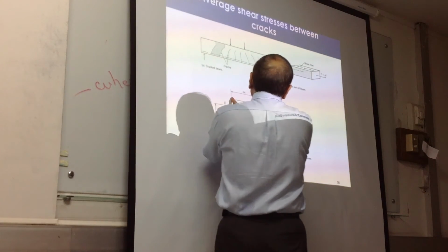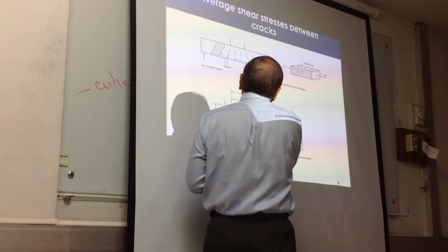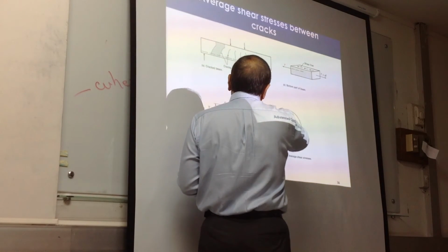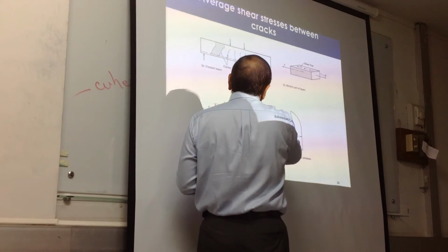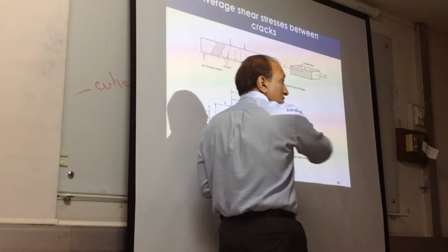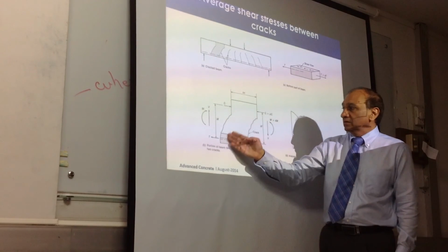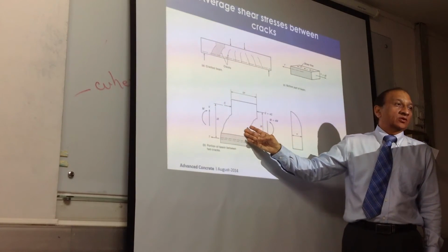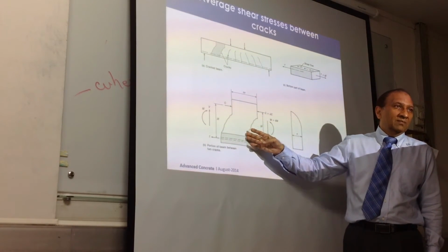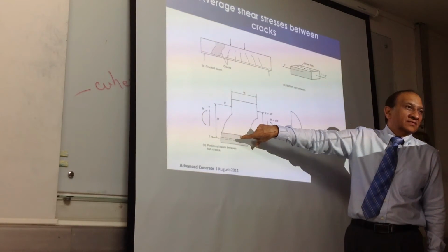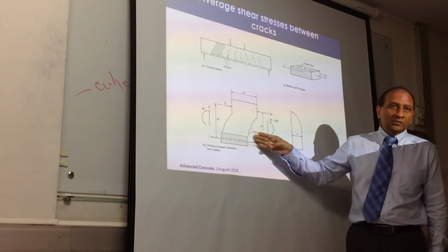Spacing. This spacing is typically related to the D, approximately. This one, nearly. This is like a square, right? But sometimes these cracks can be closer together if the reinforcement is not provided properly. But for the purpose of design, we assume this to be the case, and then we can distribute the reinforcement in between.